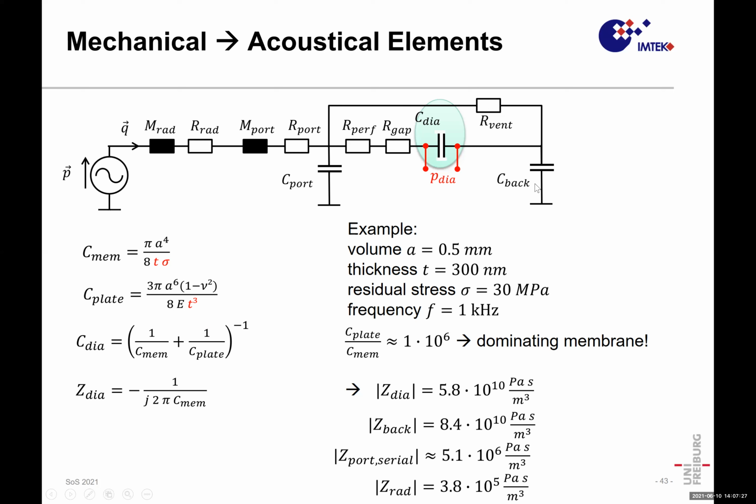In other words, in such a situation where the acoustic impedance of diaphragm and back volume is equal, we lose 50% of the energy in the back volume and 50% we can use on the diaphragm to generate a signal. This is simply a fact, and we discussed this in different aspects.